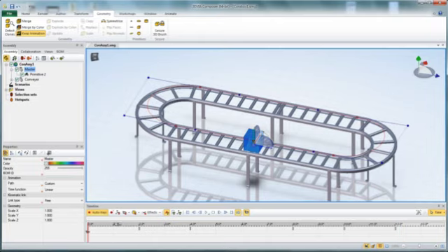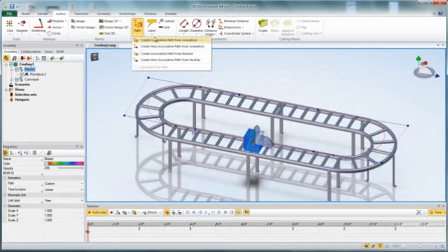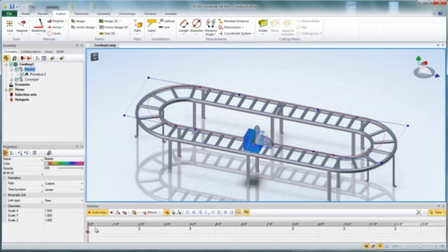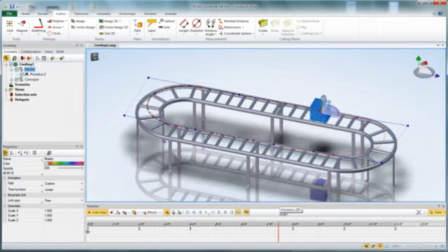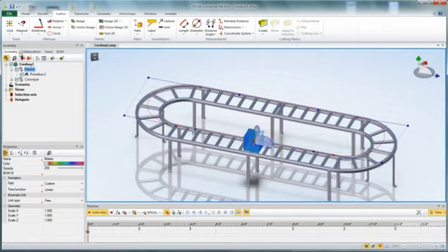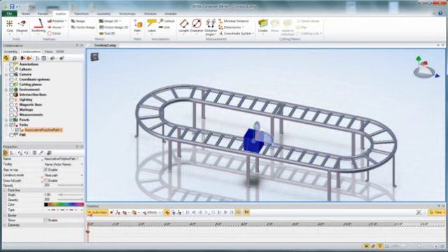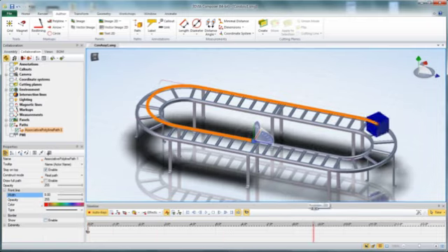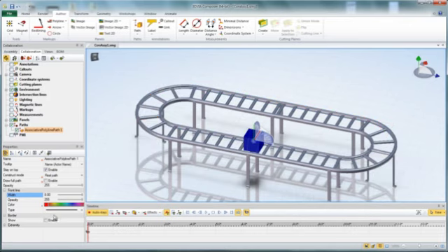So I'm going to go ahead at time 0 again and create a path, an associated path from animation, and then we'll change a couple of things on it so I can see the path being generated. And now I can select the path in the collaboration tree, or I could actually just select it by hand, but we'll make that solid and red just like last time. Maybe kick up the width a little bit so we can see that draw a nice curved path. But we can do a little bit more.